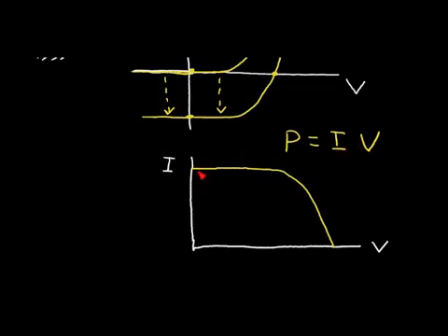So if we are operating at a point right here, or in fact, let's consider we're operating right here. At this point, we have no voltage across the solar cell. So we've, in effect, shorted out the solar cell, and we produce a large current. But since the voltage is 0 in this equation, we don't really get any power, so it doesn't do anything useful.